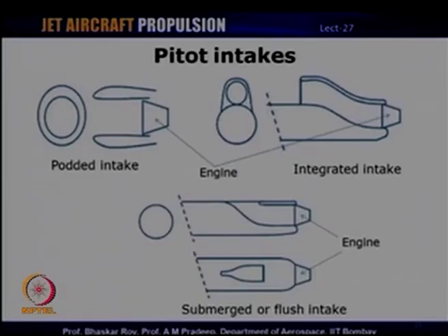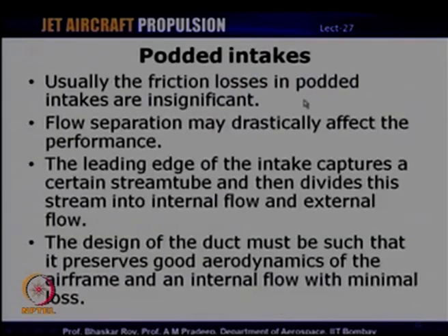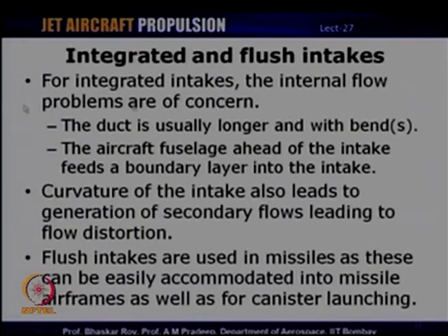So, these are two limitations. One is the fact that there is a longer duct here, which means frictional losses would be larger than in podded intakes. At the same time, there are possibilities that the entry flow to the intake itself has non-uniformities. The curvature of the duct in this case may lead to generation of secondary flows, etc., which can cause even more inflow distortion to the compressor.